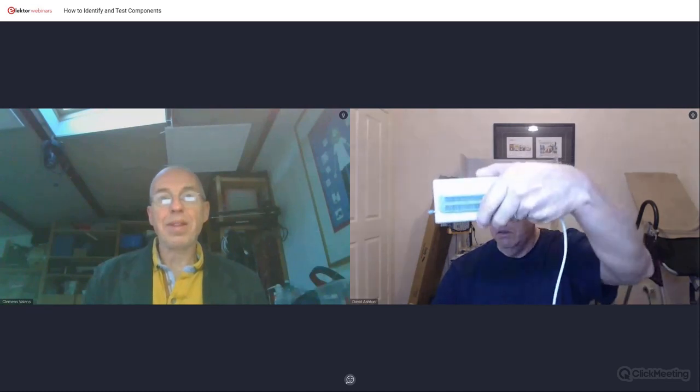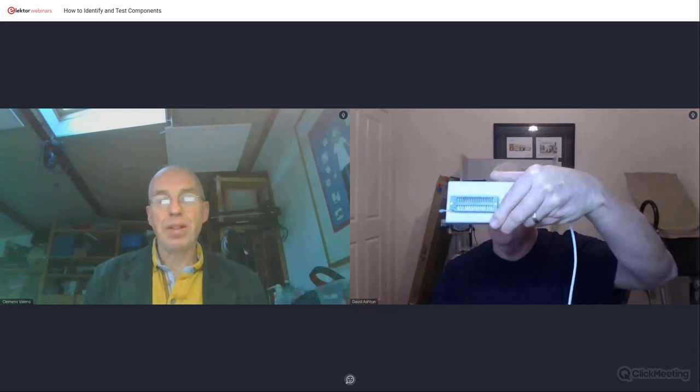Okay, there are various versions. The current version, which is what this one is, is called the TL866II, with a Roman numeral 2 after the part number. That's really the only one you'll find these days. They're all very similar, but the only difference really is the software. As I said, the more modern ones can't test or program very old EEPROMs like 2708s and stuff. But I bought this primarily as a logic IC tester, and it's pretty good at that.